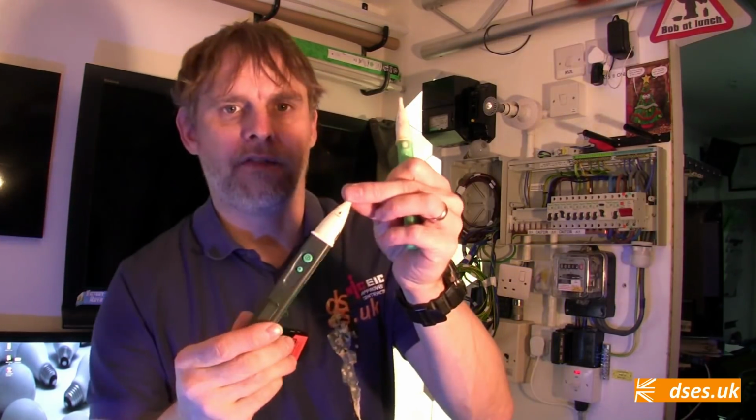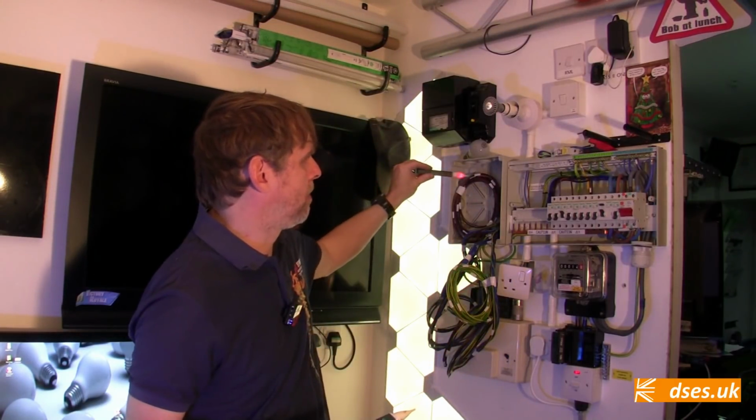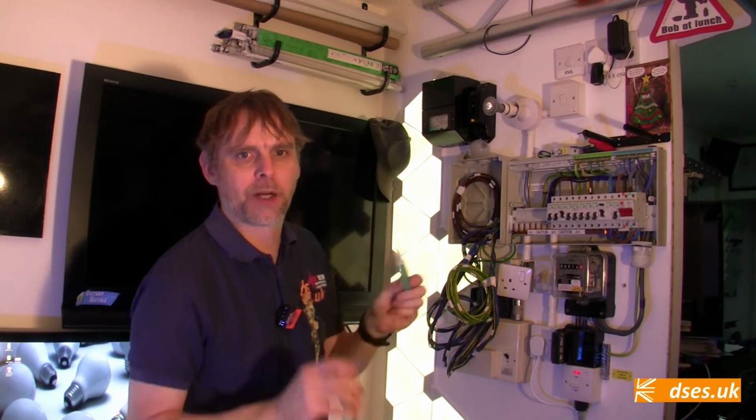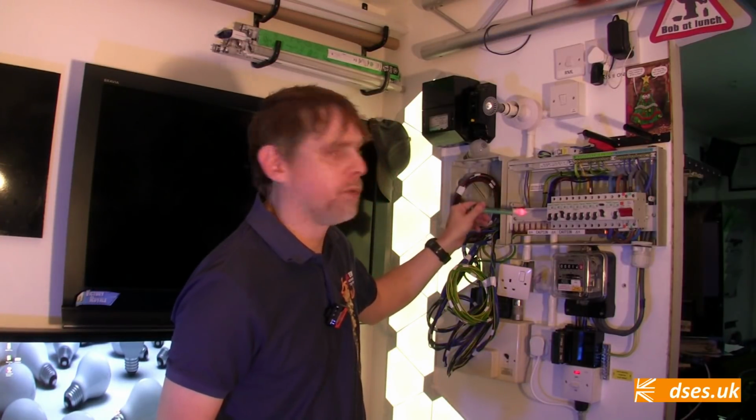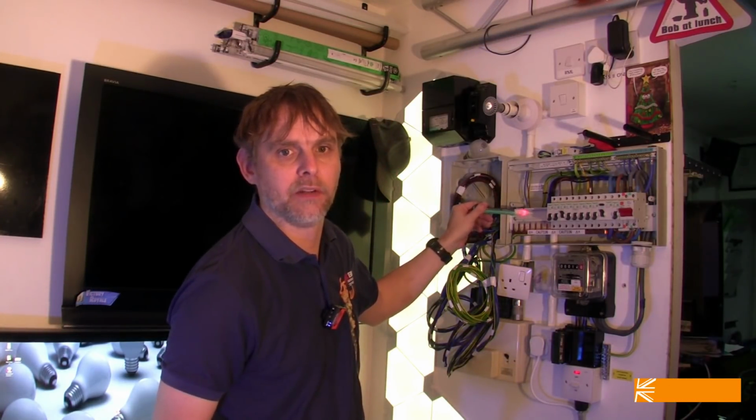I should also mention that one with a power button and active indication is better than one without. The Q-Stick Duo has a visual and audible heartbeat to let me know it is on and active, but the Uno model has nothing. The Uno model simply lights up when placed near a voltage source. But if the batteries are flat, then it won't work, and I have no way of knowing if that's down to a flat battery or because the wire I'm testing is dead. I have to place it near a known live source to verify it's working in the first place. But anyway, I'm going off topic. Suffice to say that non-contact indicators are useful as indicators of a voltage being present, but are not suitable for proving dead, as they are fallible.